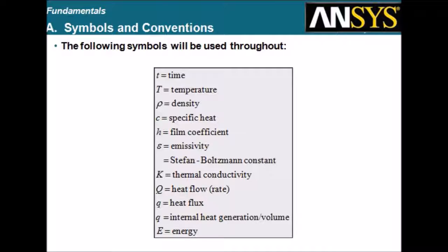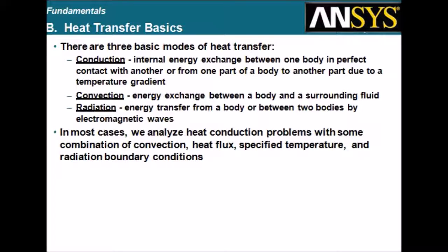Internal heat generation per volume. Energy. There are three basic modes of heat transfer: conduction, internal energy exchange between one body in perfect contact with another or from one part of a body to another part due to a temperature gradient; convection, energy exchange between a body and a surrounding fluid; radiation, energy transfer from a body or between two bodies by electromagnetic waves. In most cases, we analyze heat conduction problems with some combination of convection, heat flux, specified temperature, and